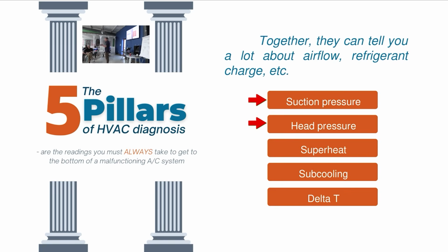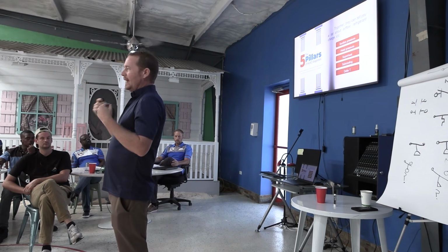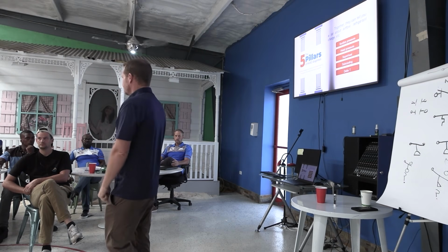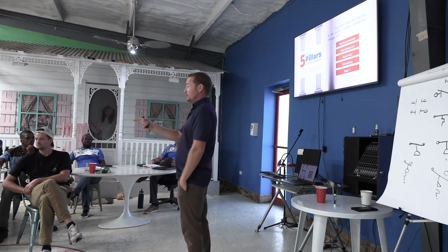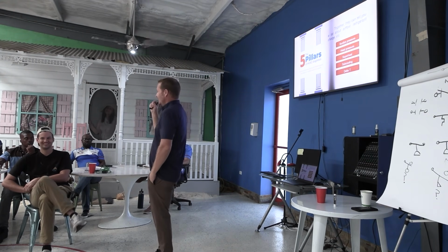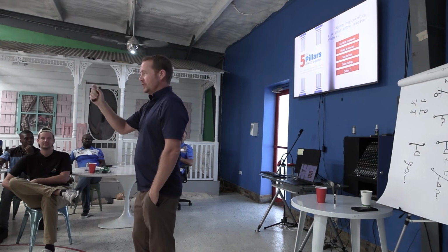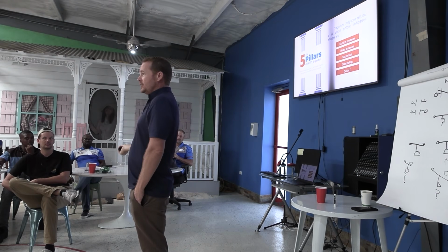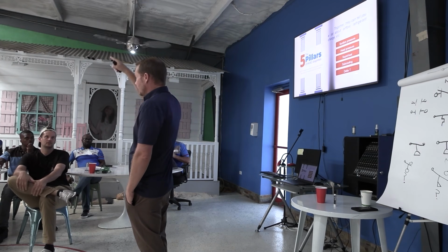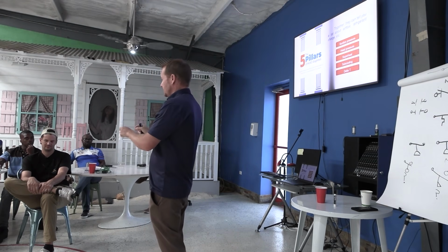When I say suction pressure, what am I really saying? When I ask for suction pressure, when you communicate suction pressure, what are you actually communicating? Simon jumped right to it, and he's cheating a lot because he's listened to me a little too much. Most people will say, okay, suction pressure, well, it's suction saturation temperature, right? SST. So you take the pressure, and on the old gauges, you would look at the needle, and it would point to, based on the refrigerant you're working on, or on the PT chart, the saturated suction temperature.